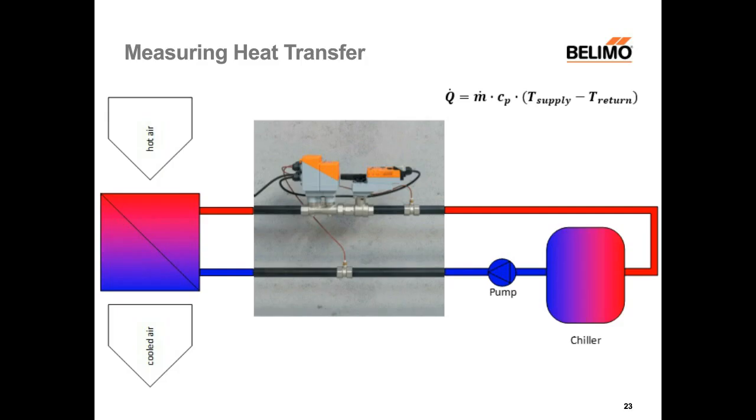So now we got the second chapter through, and now we come to the insights. During the fundamental session, we learned the formula for the heat transfer Q point. So measuring the temperatures is pretty straightforward. Anyone can do that. The Cp for water, the heat capacity, is almost constant, around 4 kilojoule per kilogram by Kelvin, or 1 BTU per degree Fahrenheit and pound. But measuring the flow is the challenge.